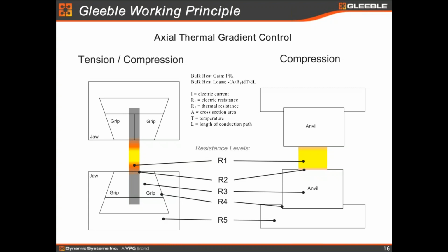The Gleeble itself, as a thermomechanical simulator, is not really that difficult at all if you understand the principle. After all, there are two basic loops. One is the mechanical loop, right? Tension and compression. That's it, nothing else. If you have a Moog valve, a hydraulic valve, you can do tension and compression, no matter what. Very simple. Of course, if you want to make a high speed, then there are some tricks.